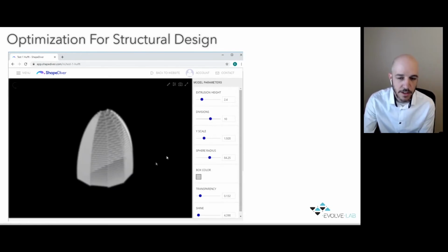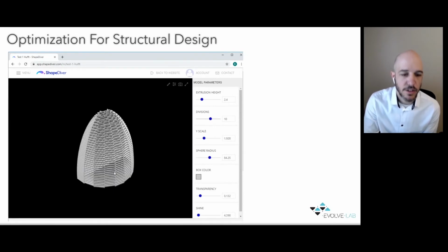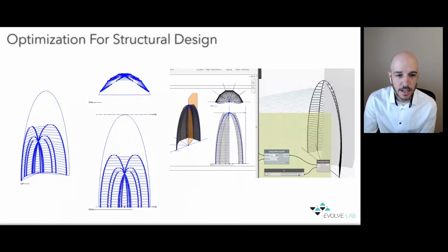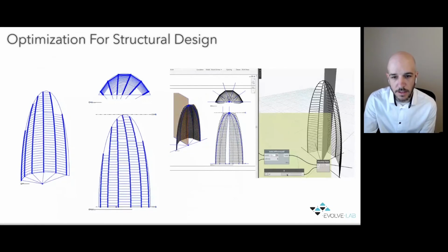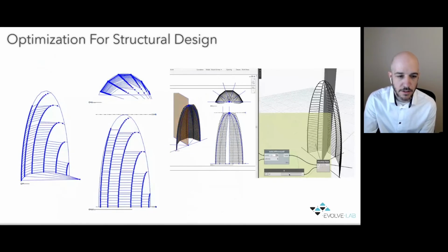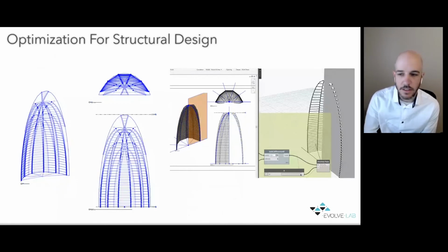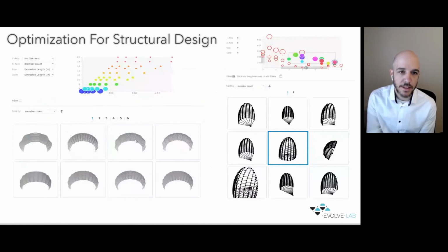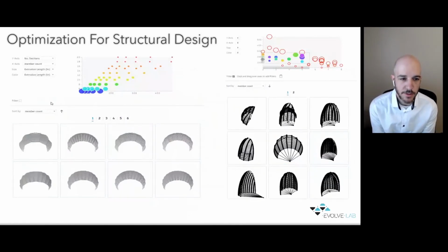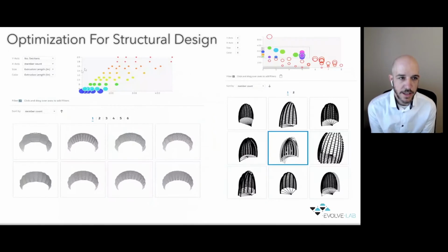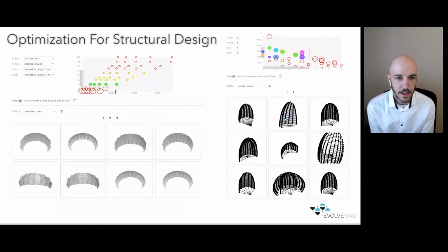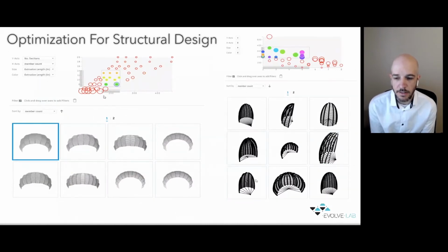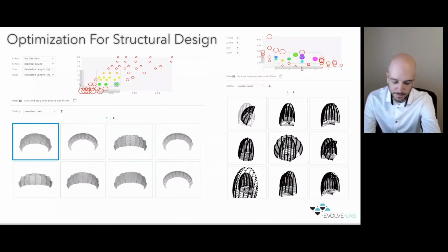It was pretty successful, but we wanted to flex the muscles a bit in the new generative design tools in Revit. So we started to bring the project into Dynamo, starting to look at the forms, the divisions, seeing how the tube steel would actually interact with the edges, starting to get the tube count, things like that. And then finally, we brought it into the Revit 2021 generative design tools. And then in here, we could actually start to interrogate some of the model optionalities using a scatterplot map, as well as a parallel graph chart for the generative design process.